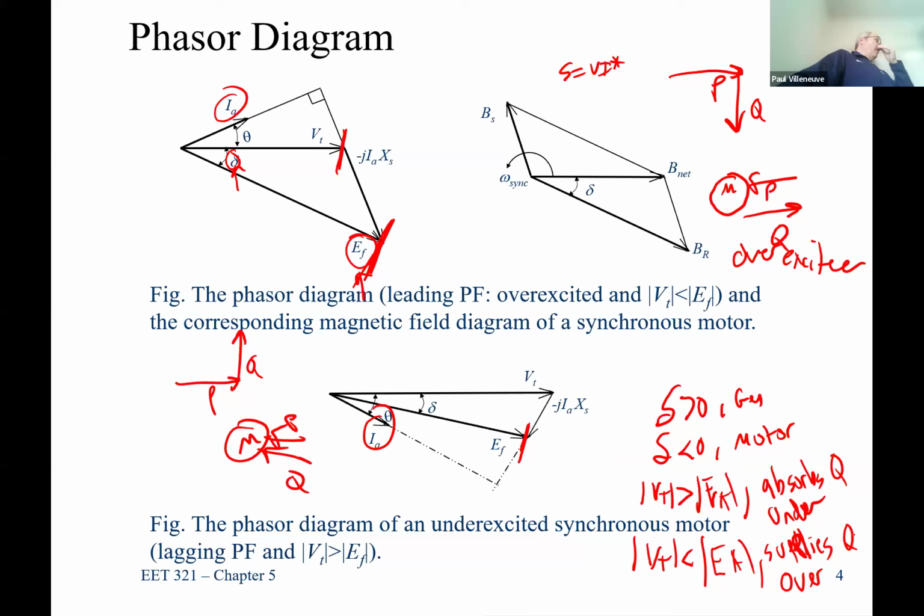And so one of the things you're starting to see more and more of is inverters operated at a specific power factor to meet utility requirements. And the utilities are taking advantage of these things to really support the grid. Synchronous machines have been doing that for 100 years. Inverters have only been doing it recently.